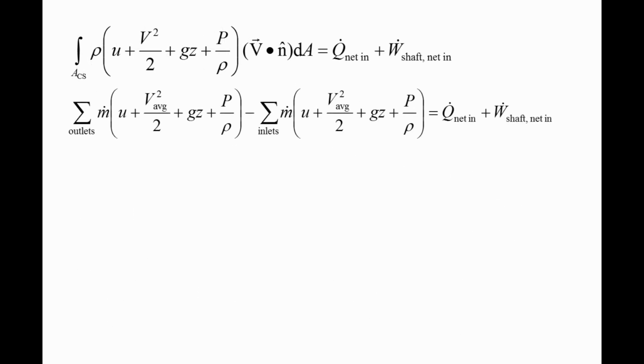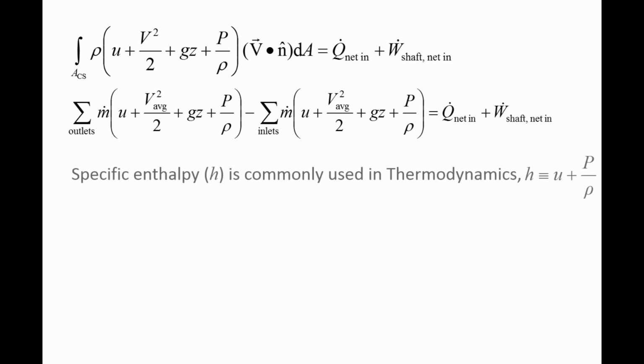Let's return to the conservation of energy equation and plug in the expression for the surface integral. At this point, we can define a new quantity called the specific enthalpy, which is equal to the specific internal energy plus pressure divided by density. We will denote specific enthalpy by lowercase h. Specific enthalpy, like specific internal energy, has units of energy per mass and is a property of the fluid.